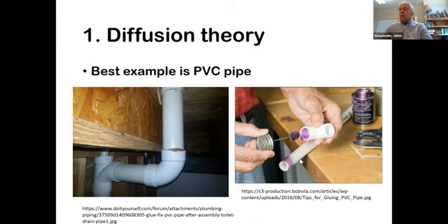So when you apply the primer and the glue, you're applying solvent and more PVC. The reason it smells is because the solvent has a high vapor pressure. So when you jam these two things together to make your adhesive assembly, the solvent's evaporating fairly quickly.